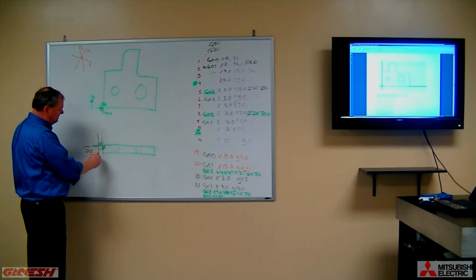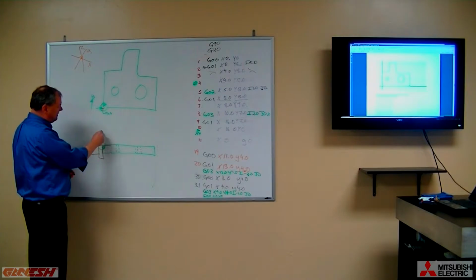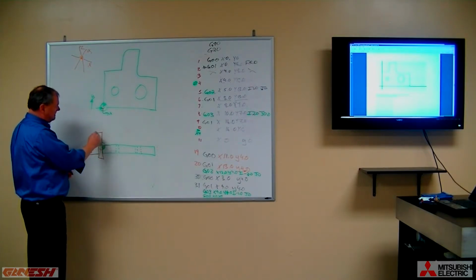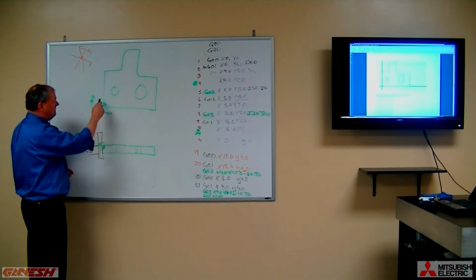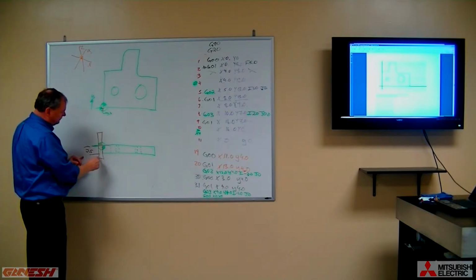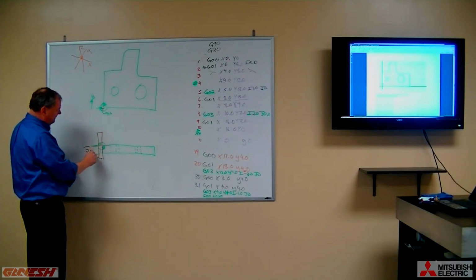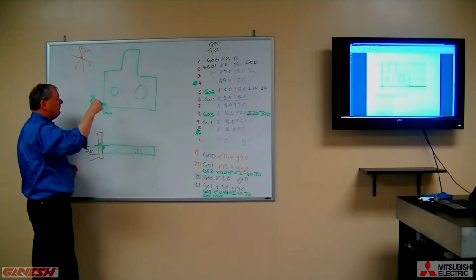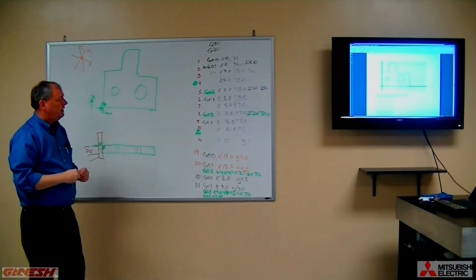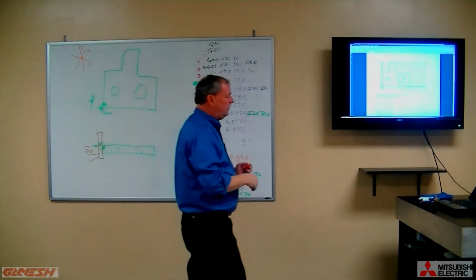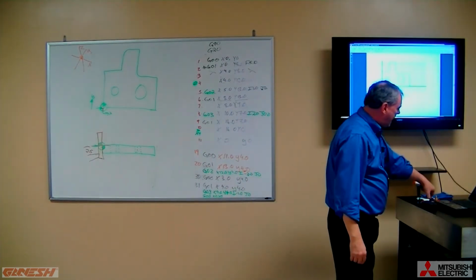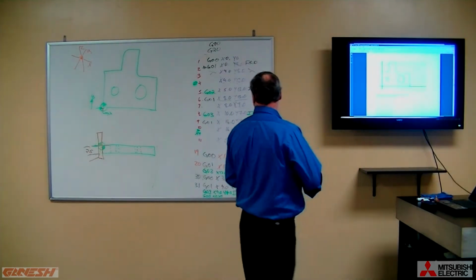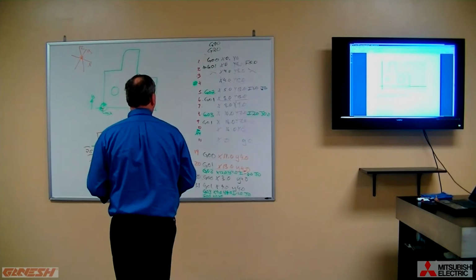we're going to tell it to move the cutter down, because remember, our cutter is a cylindrical object that will end mill as we move around, that we want to move the end of the cutter 2.5 inches down from the z origin, and then we'll finish this cut, and then we want to move it up, over, and down. So what we'll do is we'll rewrite this program and we'll add the z steps as we get to it.